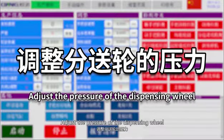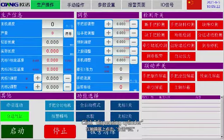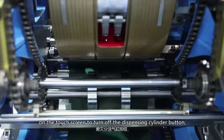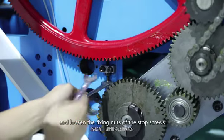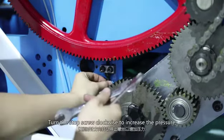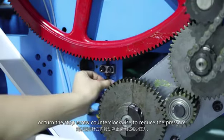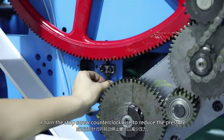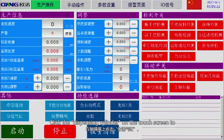Adjust the pressure of the dispensing wheel. Click the dispensing cylinder on the touch screen to turn off the dispensing cylinder button and loosen the fixing nuts of the stop screws on the front and rear sides. Turn the stop screw clockwise to increase the pressure, or turn the stop screw counterclockwise to reduce the pressure. Tighten the fixing nut of the stop screw.